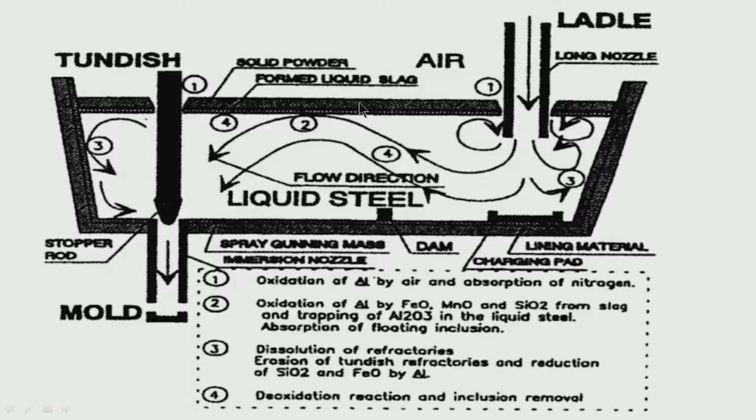So, a two-stage slag is used. The bottom slag, which is just at the top of the liquid steel, is basically a basic slag. On top of that we use rice husk, which is a good insulation material. This does not allow the liquid steel temperature to come down. So, we have a 2-stage slag.